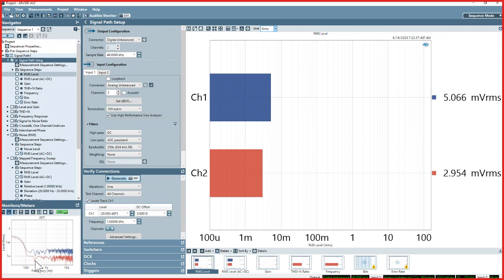Here you can see a couple things. First of all, we do immediately have signal from the device. You can see this device has a very significant DC offset. So in this device, maybe I will go ahead and select AC coupling just to remove that DC offset.